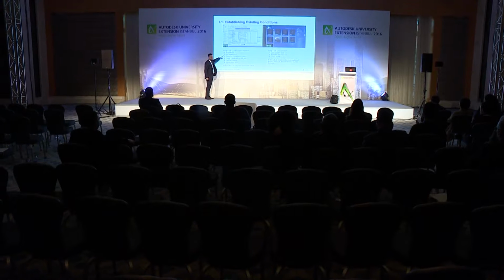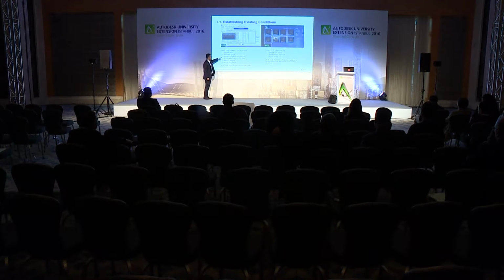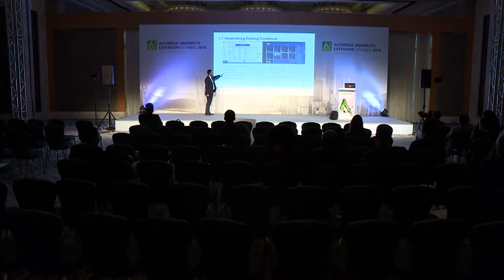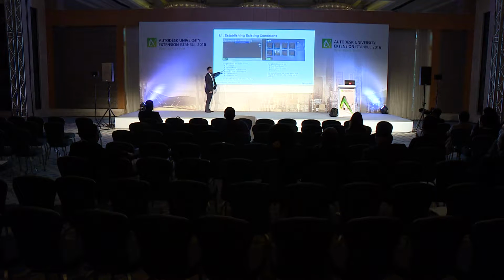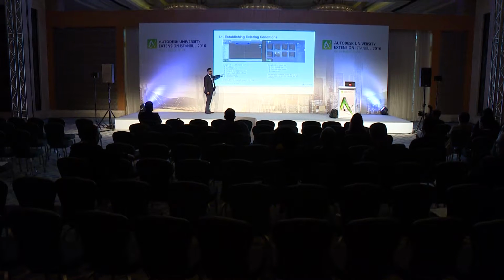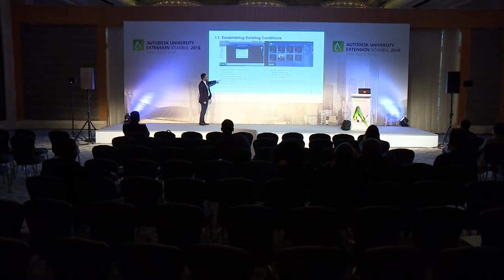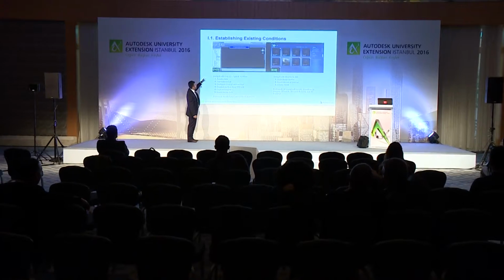the data, we translate it or we configure it. We have to configure the Civil 3D environment, tell it that we're working in this coordinate system, for instance, this system, metric versus imperial, etc. And from the data that we get, we ask Civil 3D to create a surface from the GIS data or the other data that we've got.